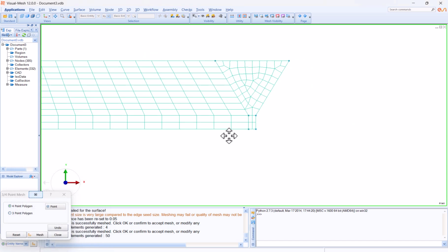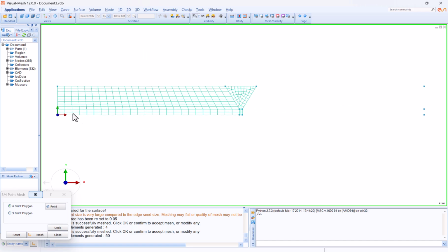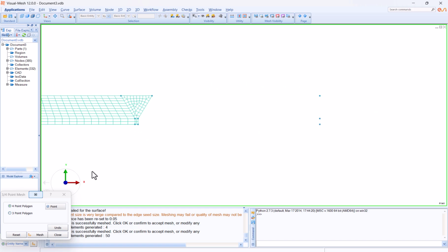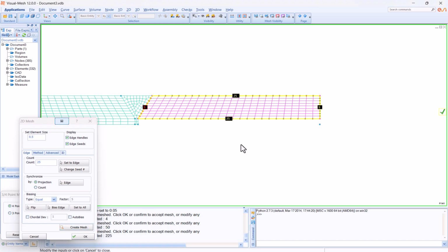It's so crucial to start with this root pass, then creating the left one, otherwise you cannot create the left part, it would give you some error. So it'd be the same right over here. We can set the edges 25, 25, by clicking on this one, left click and hold, then we drag it down, we can have 9 elements here.